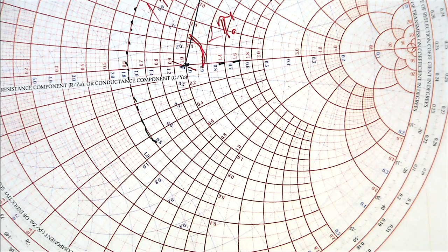Then we reach this point, and this point shows that your XC, for example, is 0.53, and it equals 2 picofarad. The same thing for the inductor: we start from this point, the length should be this value, and we reach here. So XL equals 2, and it equals 5.3 nanohenry.